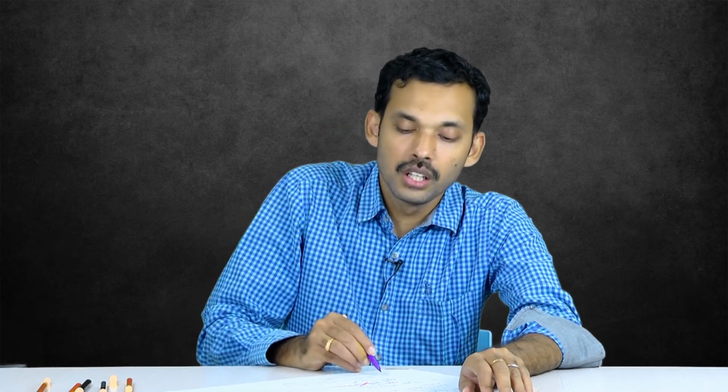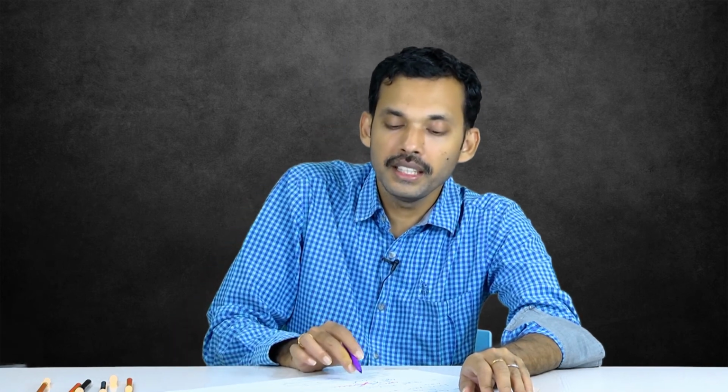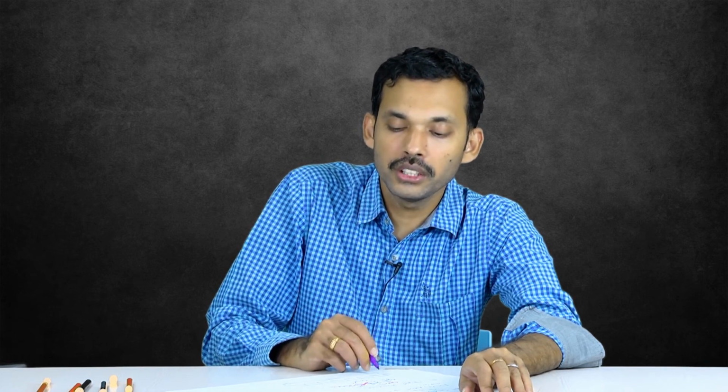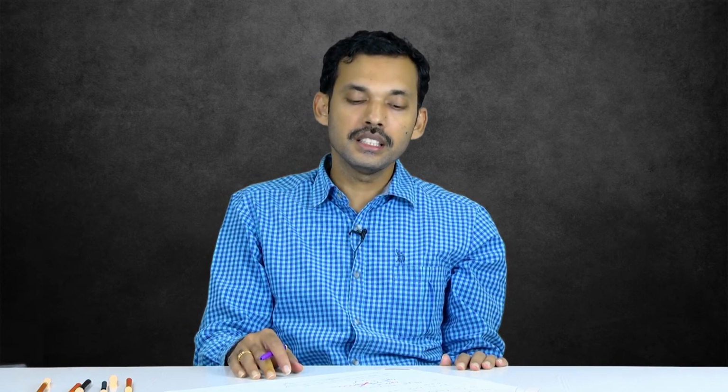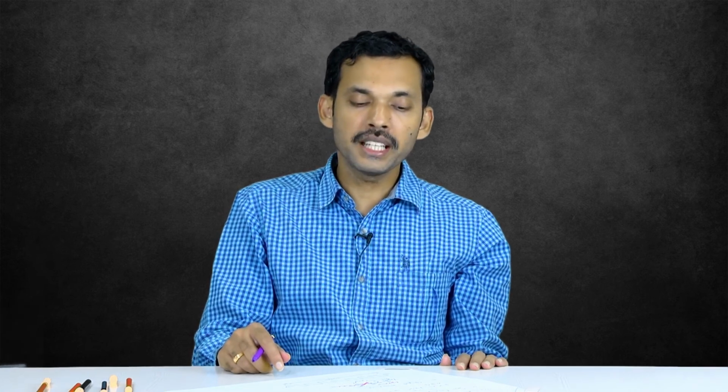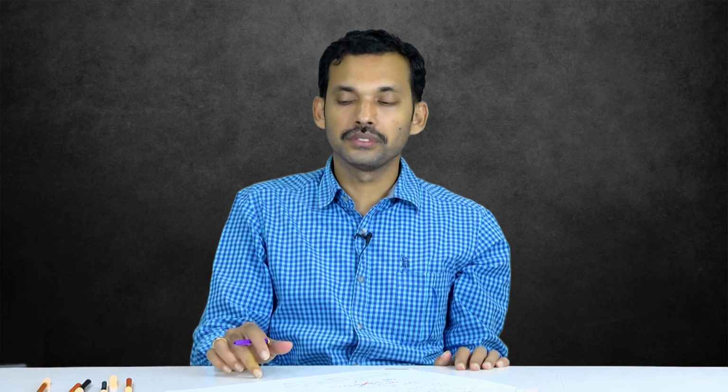Like this we can calibrate the sensor to any kind of rotations, and here you are going to get a direct output, and this can be fed inside a microcontroller or a microprocessor. So this kind of sensor is called a digital transducer, and here I have shown you a measurement of angular velocity based digital transducer.